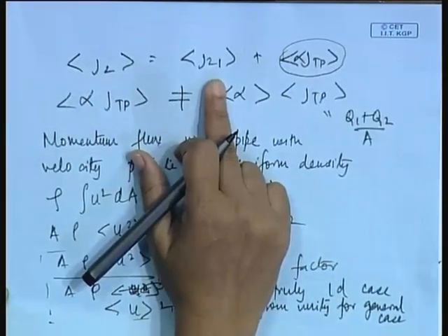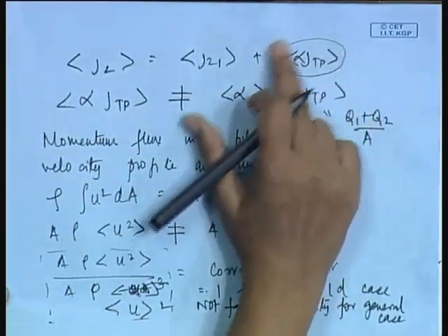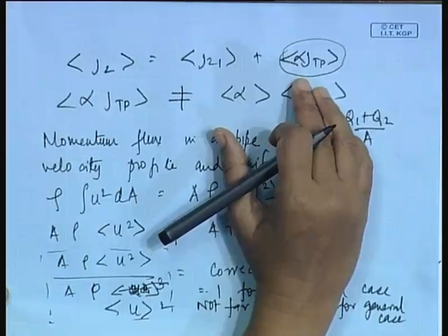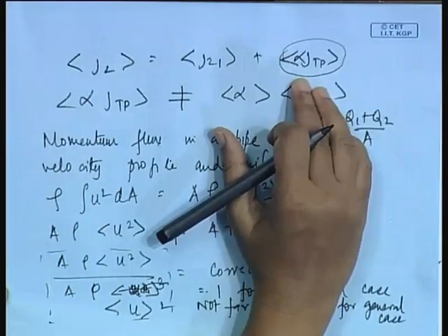This is also the area averaged value. This creates a problem. This is a product of two quantities which might vary across the cross section. So, what has to be done? The volumetric concentration has to be measured at each and every point. The overall volumetric flux has to be measured at each and every point. Then the product has to be made, and then it has to be integrated. For engineering applications, this is very, very difficult.